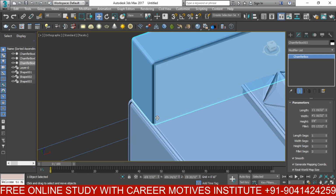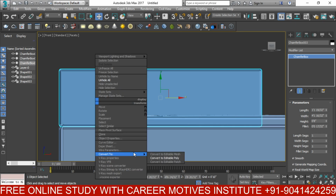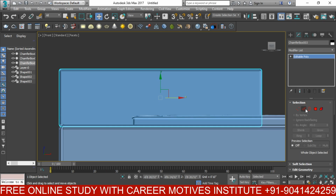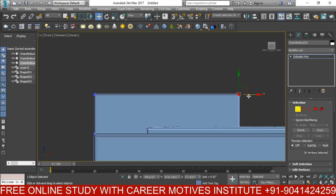Okay, and then the next step is right click, convert to editable poly. Okay, and vertex, and I'm going to select all the vertex from here, and I'm going to move this in x direction like this.